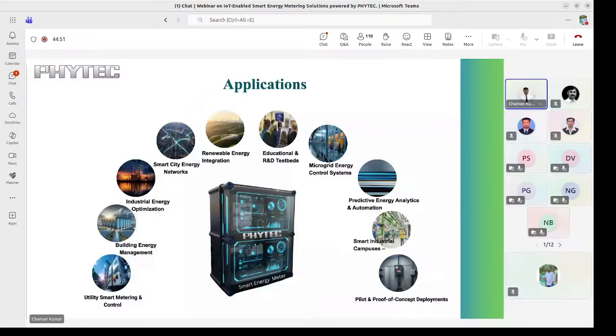Just a minute. First, the authentication is going on. It is the DLMS authentication, it will understand, meaning the AARQ and other things. Once it understands, now if I read the instantaneous profile, it is reading the instantaneous profile, and you see here. Let me read one more time, then I will show you.